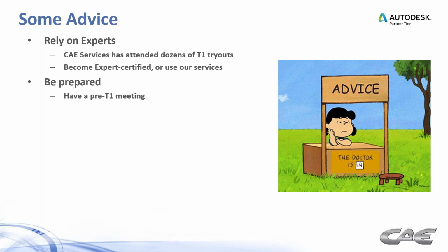Like I said, I've attended many T1 tryouts myself, and the ones that don't go so well are the ones for which people are not prepared, where there's been no discussion about what's going to happen at the press. You kind of get there and everybody's looking at each other, and then the process guy takes over and he does his own thing, and suddenly you have a big mess on your hands. So have a pre-T1 meeting.